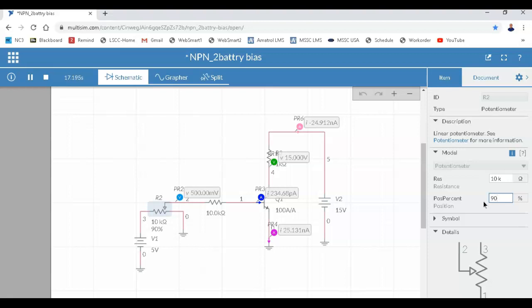Once I get it cut off, I can't cut it off anymore, right? You understand what I'm saying? So when I go down on my other side, here's 10%. It's already saturated. See, so we got 100. Once you saturate the transistor, you can't saturate it anymore. It's kind of like a faucet. Once you get the maximum flow, it doesn't make any difference how much you open the valve past that. You're going to get the same flow, right? Does that make sense?